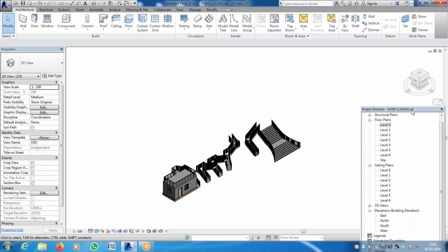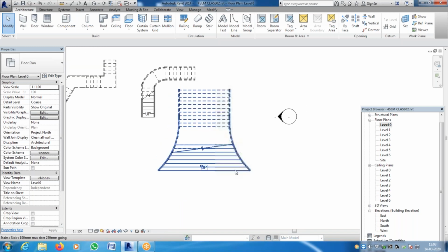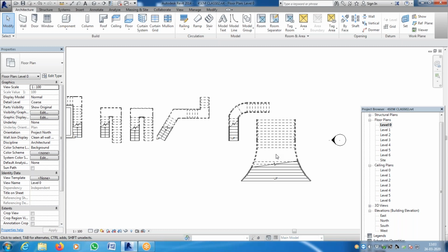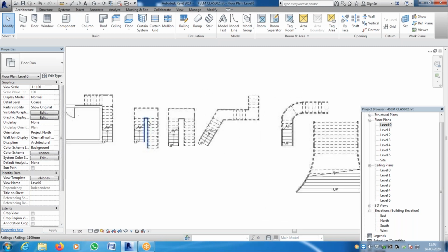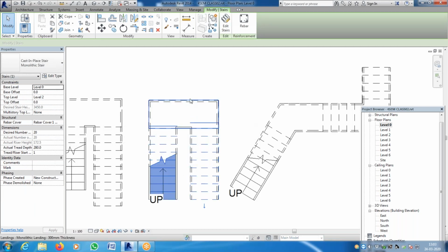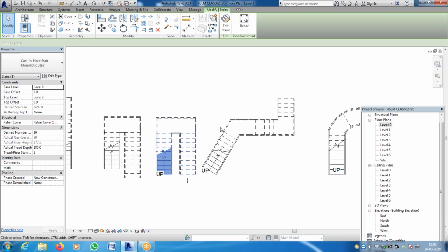Okay. One major mistake I took some time to clarify is that I tried to combine stair by sketch and stair by component. That is what I tried doing here. That's not possible. In stair by component, you can't do all this relatively flowery design over the landing or staircase. Stair by component simply depends upon three main factors. One is the run, another is landing, which can be automatic or not automatic, and that's about it.